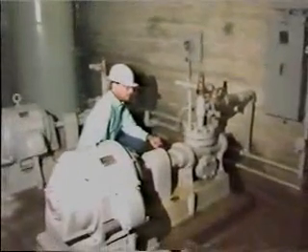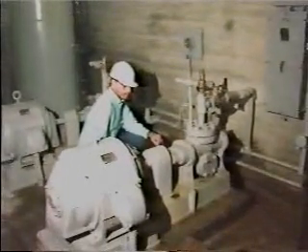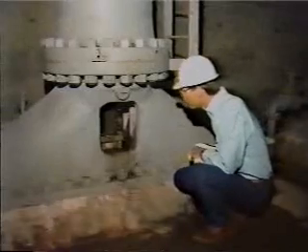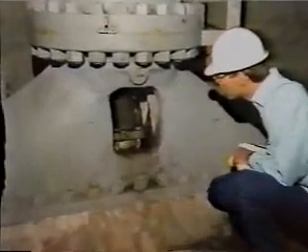Examine the pump and fluid lines for leakage. And check that the hydraulic reservoir has enough oil in it. Now check the piston rod or actuator for leakage. Also look to see if the piston rod is scratched or scored. If it is, dirt has probably accumulated in the packing or wipers.